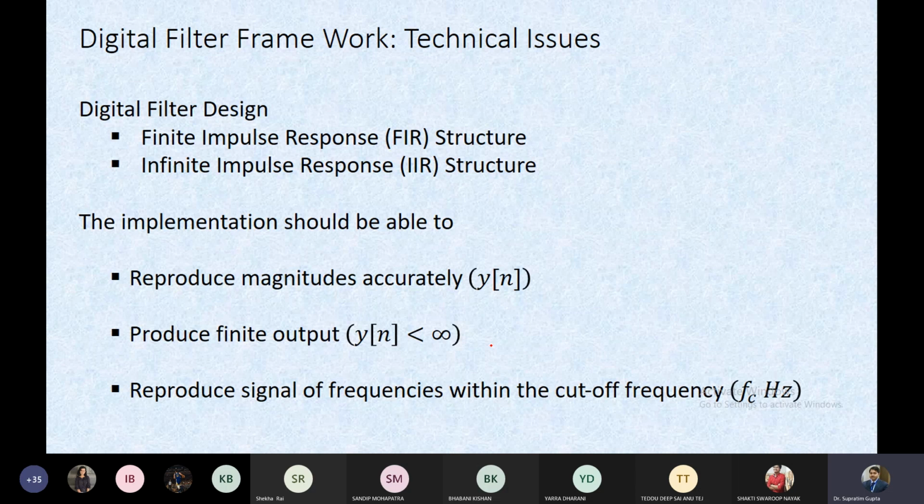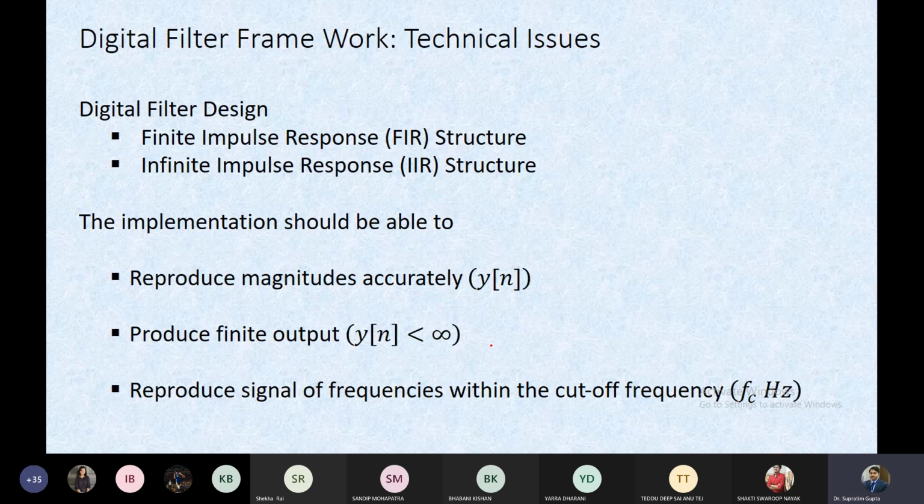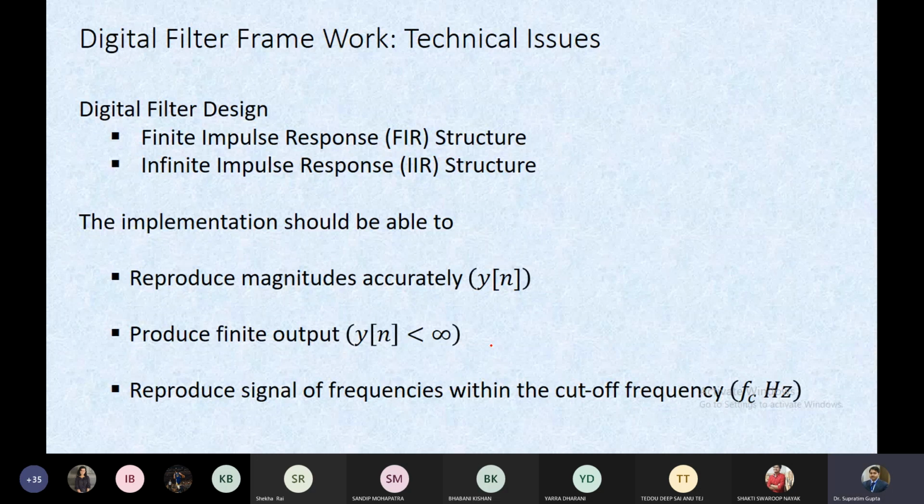Depending upon that, say for example, I have one value 5.23 and another value 5.232. But when we use a rounding off technique to round it off up to the second decimal place, we find they are the same. Now if that happens for the poles of your filter implementation, two poles which were actually separated from each other, giving a certain frequency response, now because of this imprecision in data representation appear at the same location, and therefore the frequency response will change.